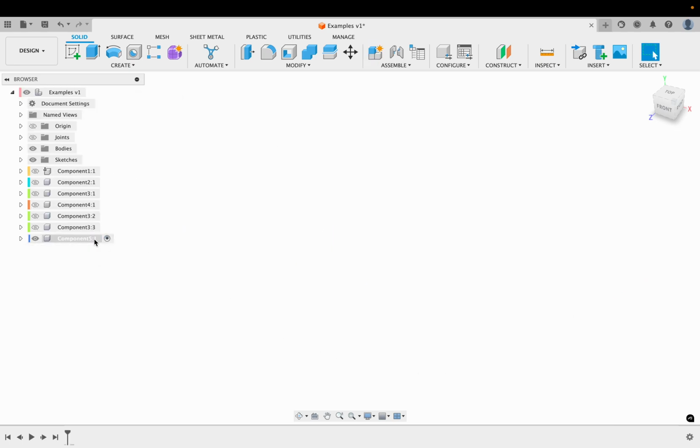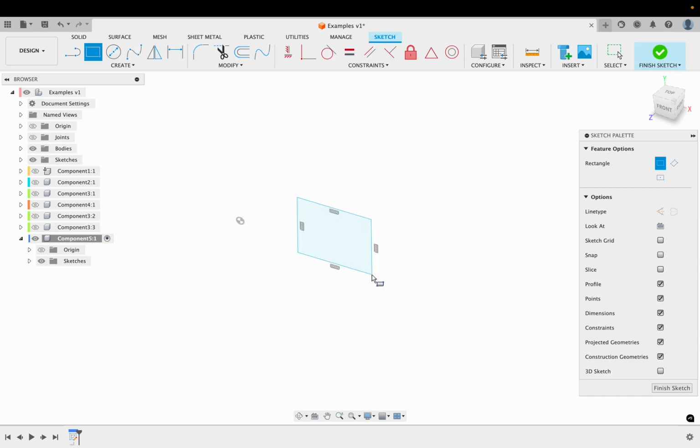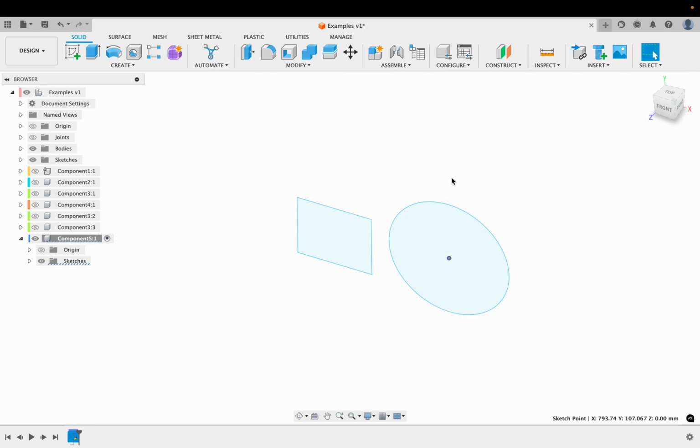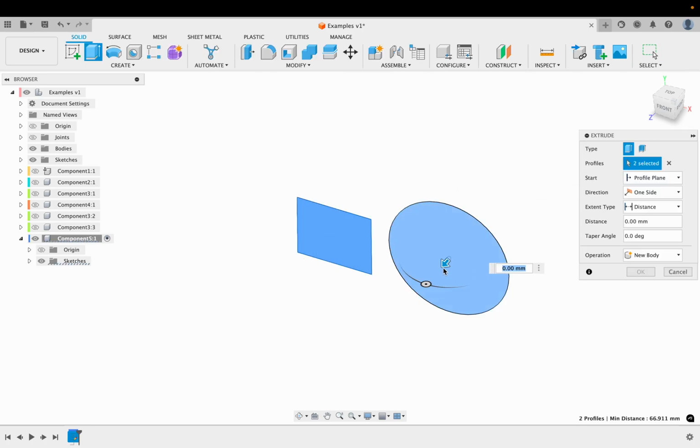That gives you this. Let's say I want to have one sketch that defines two different things, which will then become two different components. That could happen, right? So then I'll just make my sketch in this. This is highlighted by itself, so I'm just going to make this, and then maybe I'm going to make something round and something circular, like that. If I hit extrude, I can select those two profiles, and I can extrude.